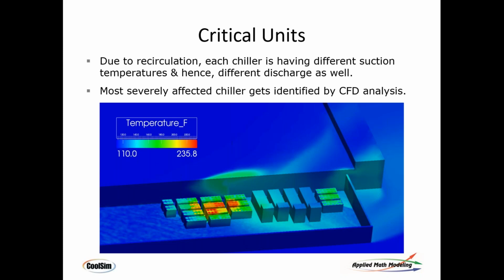It's a math model, and you can experiment with it fairly easily and test different parameters. For example, is wind the most important parameter we're facing here? Or is external temperature the most important parameter? And by wiggling one and holding everything else constant, you can understand the sensitivity of the design to that particular parameter. In design, it's called sensitivity analysis, and it's done with a variety of methods. But one method is just try it and see how it affects it in your model. And so testing different parameters is a way to know it.